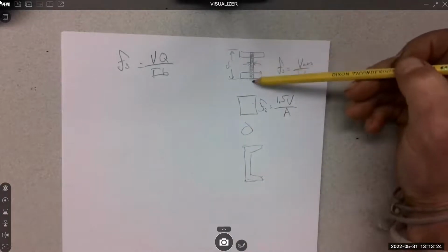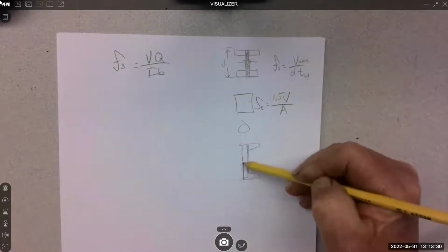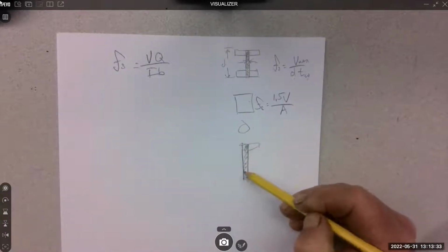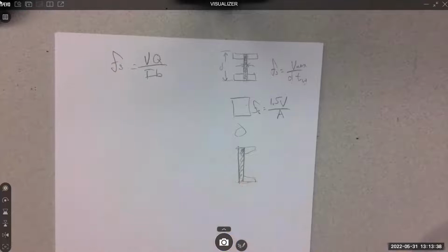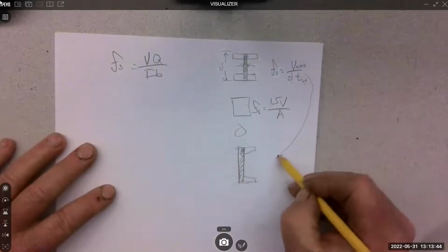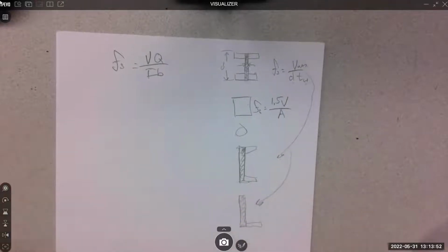It is the rectangular section of the W shape. So the shortcut for this one is the same thing. It's the rectangular section of a C shape. Yeah, this is a C shape. L shape would be the same thing. So this again would be that. And then an L shape is again that big rectangular piece. So anything that's kind of tall and has flanges sticking out, the shortcut is just the vertical web area. That's all labeled in the tables the same way as for the W.